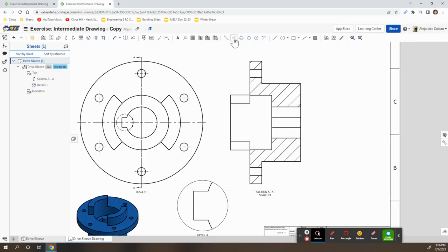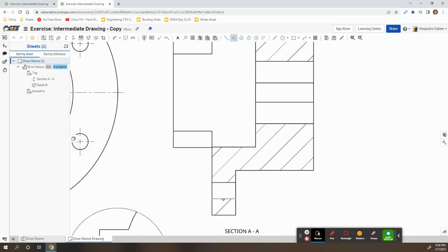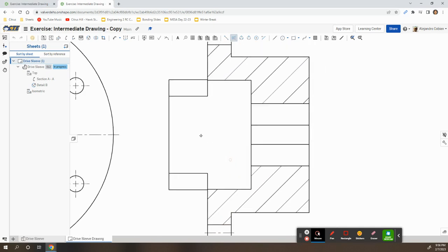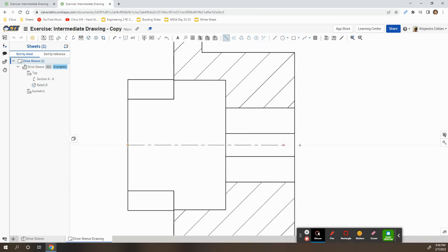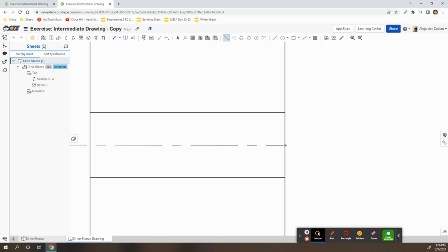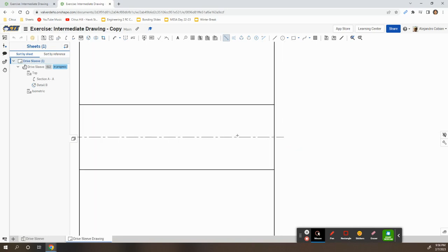So for these right here, we're just going to click here. So notice it's edge to edge center line. So I'm clicking on this line, and I create that edge. And then I do this and this. For this center point right here, I'm going to go ahead and switch this up to 2-point center line. I'm going to find the middle section here, and I'm clicking where a triangle appears. And then I'll do the same for this section over here, right where the triangle appears. And that's my center line.